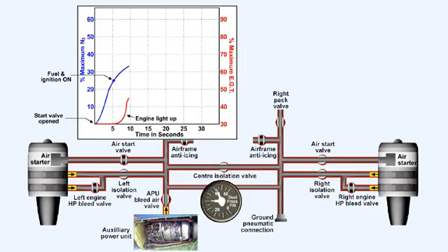The initial increase in EGT is quite sharp, because as combustion does not occur immediately after ignition is selected, there is an initial build-up of fuel in the combustion chamber. Once this fuel does ignite, it tends to overpower the cooling effect of air being fed from the compressor. Once the excess fuel is burnt off, however, and the fuel-air mixture becomes more balanced, the increase in EGT steadies. The gas which is being produced in the combustion chambers now adds impetus to the turbine blades, which eases the task of the starter motor, and the engine continues to accelerate.